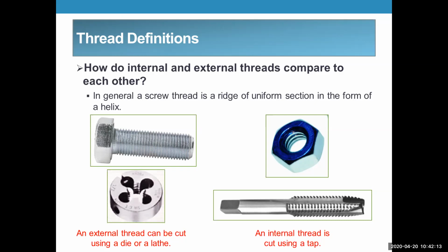It seems to me that especially when you get into smaller diameters, whatever type of die you would have in there that you could possibly even try to roll that thread with would not be very strong. Yeah. With the pressure that's required to actually upset the metal when you're rolling a thread, a die that would fit inside that hole would, even if it were supported well on both sides, I think there'd be too much flex in the tool. Yeah, the tool would crack because it has to be hard. Right. It has to be hard, and there's going to be a lot of pressure on it.